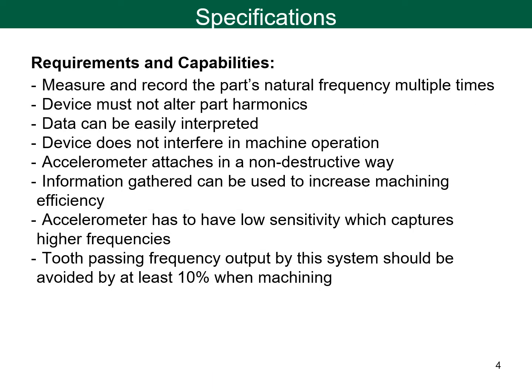Specifications: the device must not alter part harmonics, and it must not interfere in the machine's operations. The accelerometer must attach in a non-destructive way and must have low sensitivity in order to capture higher frequencies.